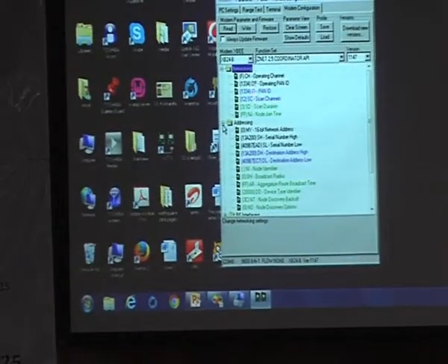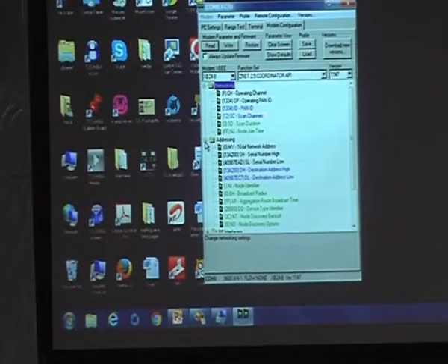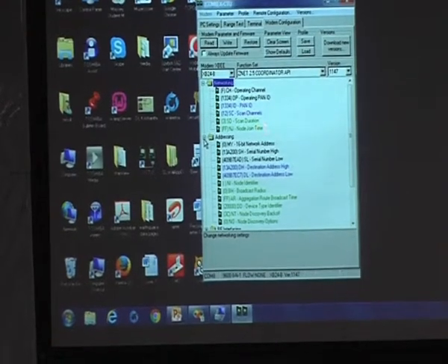So, here the important thing is that on the networking parameters you need to set the PAN ID, which is a 64 bit address, and you need to set the scan channels. These are the two important parameters that need to be set. Coming to the addressings, if you are trying to communicate with a particular sensing node as the destination, you need to set the corresponding destination address high and low. And coming to the next one,